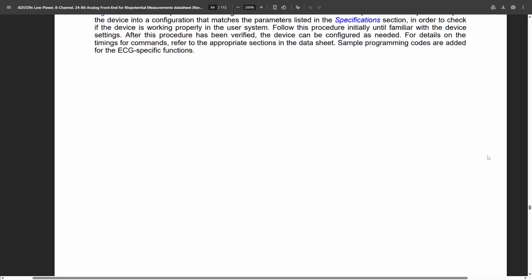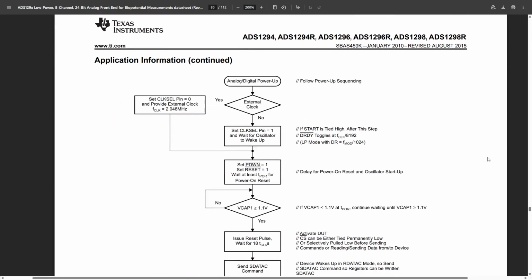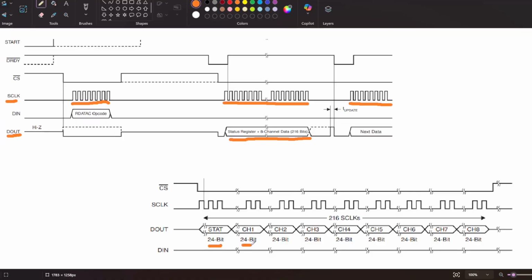Of course, we don't need to perform all these tests every time we want to measure EMG. And once everything has been tested, our real firmware can be much easier. So basically, after the initial testing, we can configure the ADS1298 with the settings we actually want, start the conversions, wait for the data ready pin and continuously read the samples through SPI.